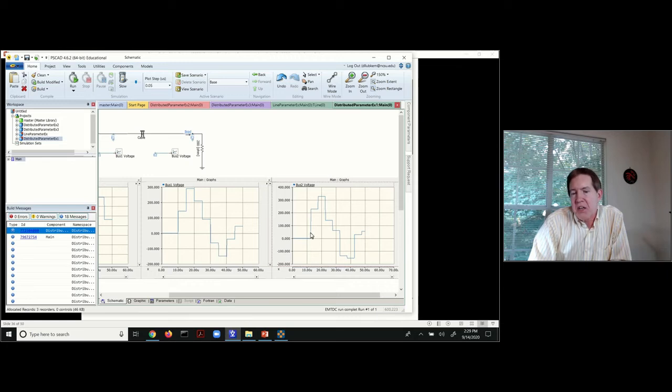And so what you can see is this voltage jump up, and then we get a reflection back toward the overhead. It hits the transition between the overhead and cable. It comes back toward the load side, and we get this second transition on here. And then if you keep running this longer and longer, you could see more detail around this. But really, what we see is what this peak value is going to be, and that's really what we're interested in this particular case.